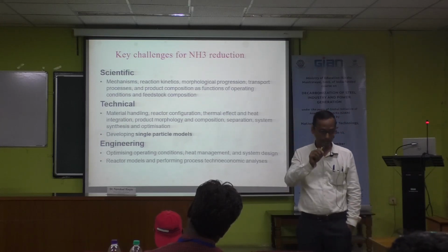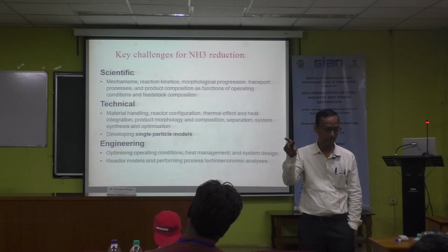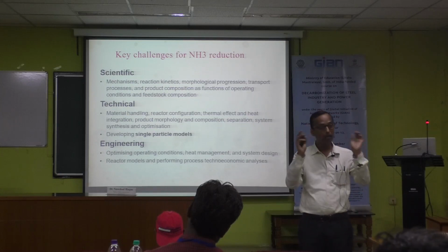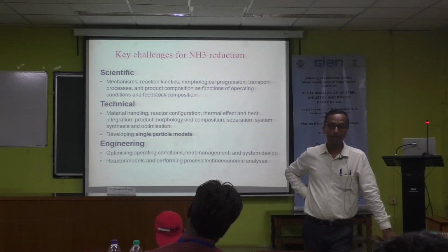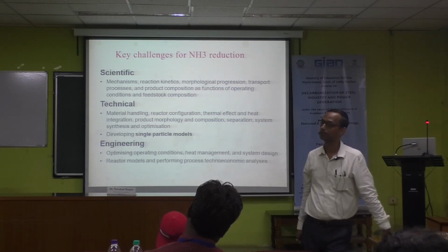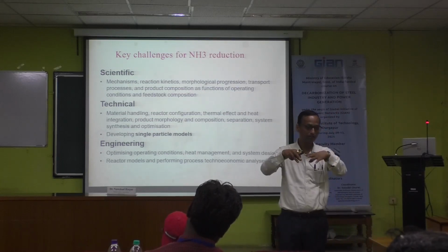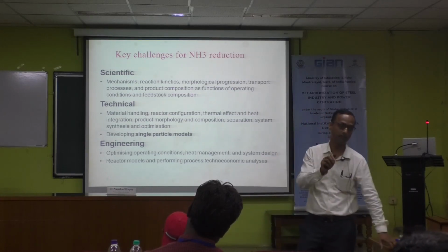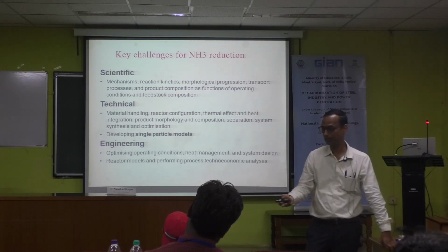If you change the temperature, and obviously the partial pressure of H2 or H2O, it will change the reaction mechanism and kinetics. Therefore, how to heat throughout the bed is a challenge. In a normal shaft reactor, if you charge the iron ore and inject the hydrogen, it will not reduce as per your requirement.